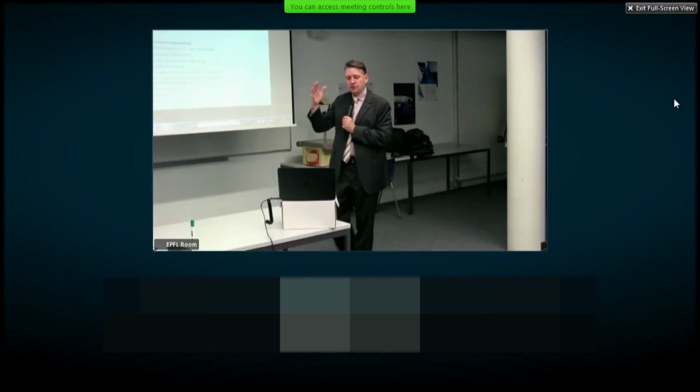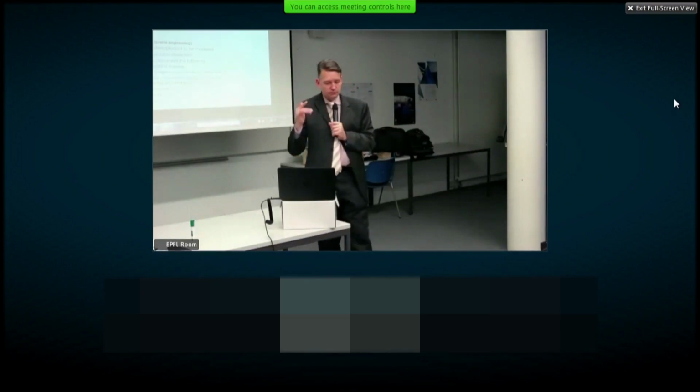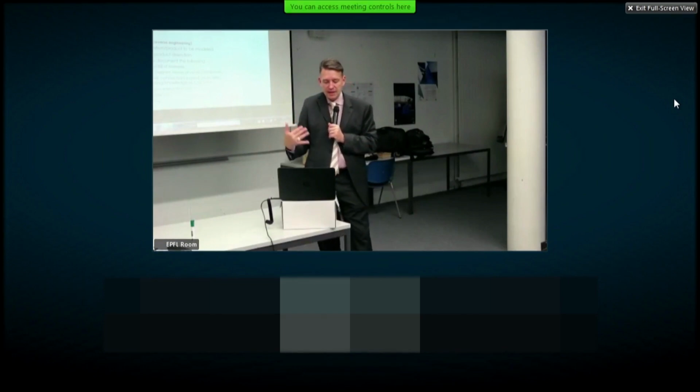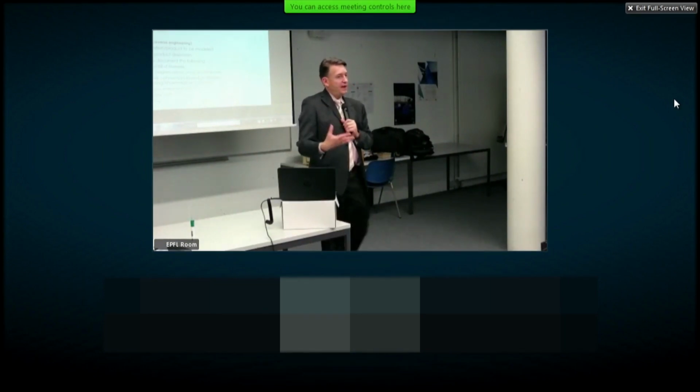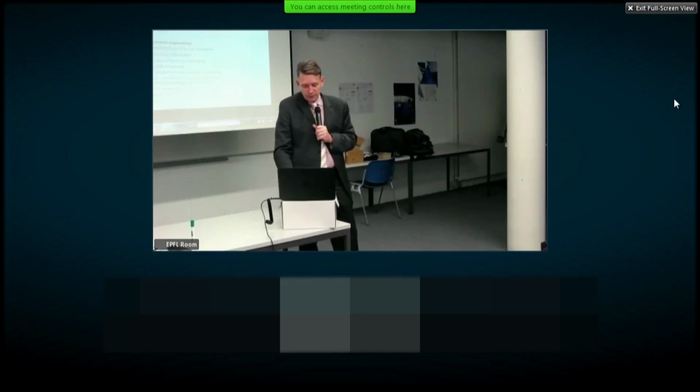So top-down, you start with a model of your system. And we talked about those system modeling languages like SysML, or in this case, OPM. And then you hide some things. You hide attributes and states. You collapse all your processes into these tagged structural links, and then you generate your DSM. And then the other way to do it is bottom-up, where you already have a design or a system. You decompose it. For example, you do product dissection. You do your bill of materials or your parts list. Then you do your liaison diagram, right? You show the physical connections. And then on top of those physical connections, you map your mass, energy, and information flows. And once you have that, then you can start manipulating the DSM. You can group components differently. You can show modules and so forth.